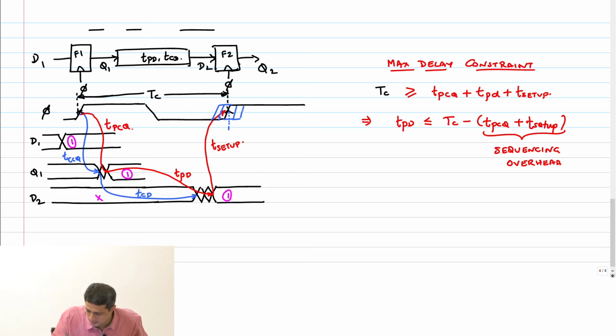So for example, I have shown you a band of curves here, right? A family of curves. Clock skew is basically the worst case delay. What is the worst case offset that I can have? That is called clock skew, T skew.